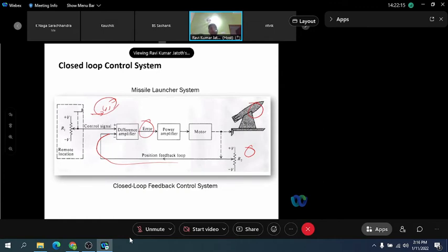So it is an open loop system, but there can be an AC which is intelligent, in the sense that it knows the temperature of the room. If it is more than, let us take, 26 degrees, then it starts working, and if it is less, like 24 degrees, then it stops working. That is how you can save power. They are called intelligent, right?